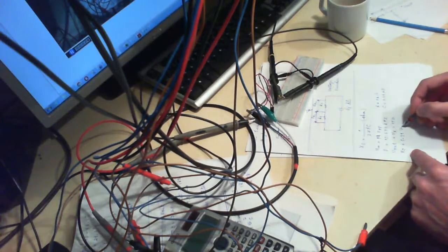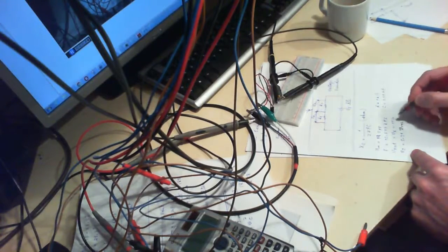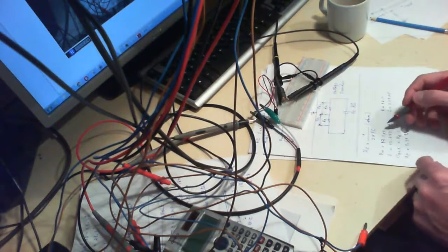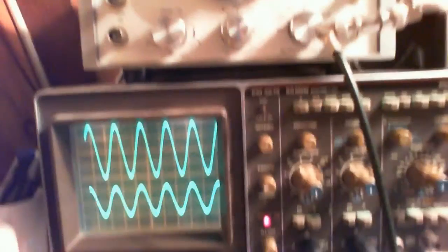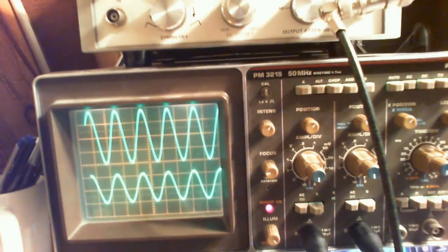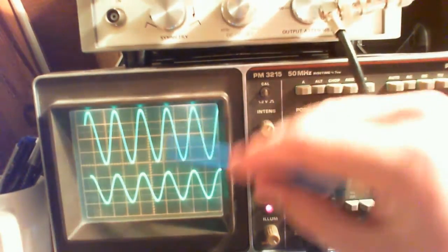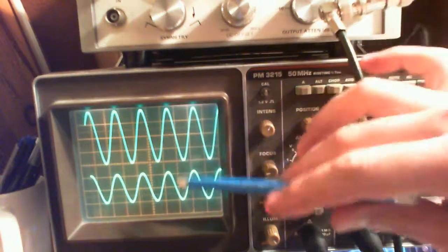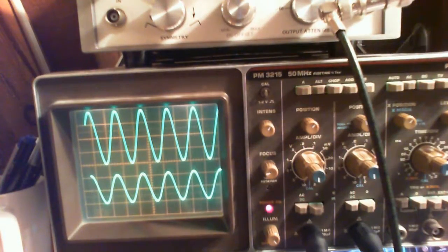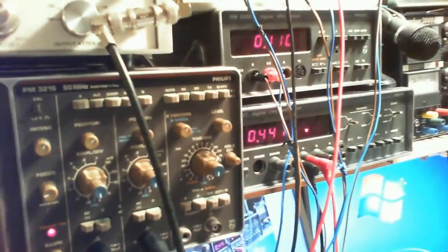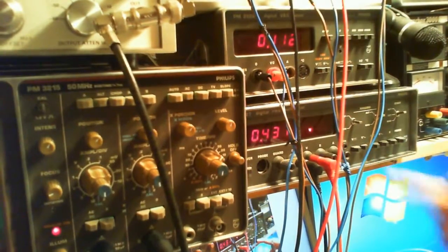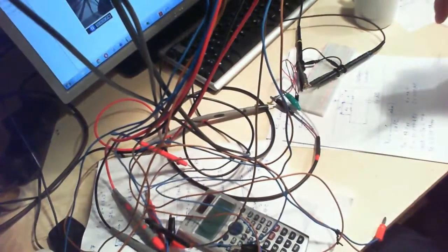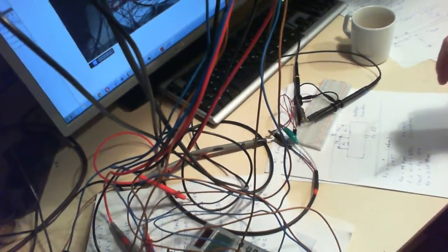It's an RMS voltage. It's VRMS. But for example, the V of in that we measured with the oscilloscope over here, this voltage that we measured from this peak to this peak, the oscilloscope is showing us the peak-to-peak voltage. But the voltage that this multimeter is showing me, that's the RMS voltage across those 2 points. So you need to be aware of that, so you don't make any wrong assumptions in your circuit.